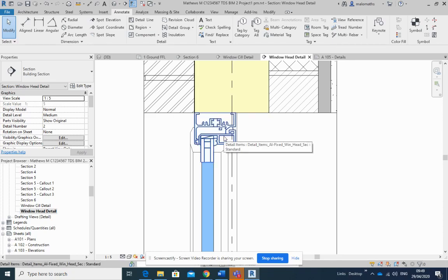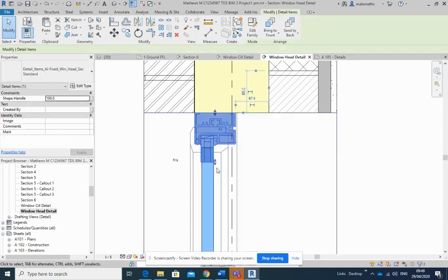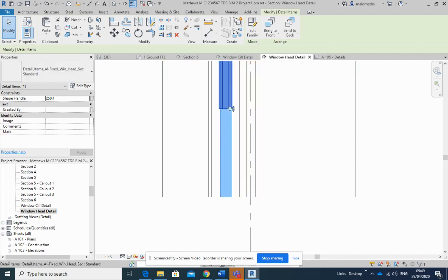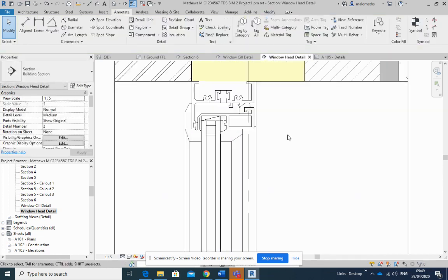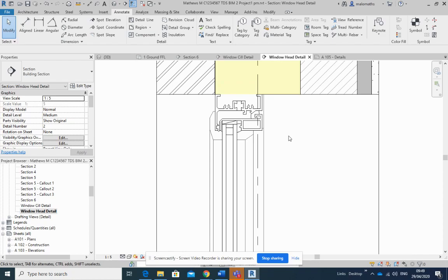This is quite a handy little 2D as well, because it has stretching grips and things like that. So look, I can stretch that double glazing right down past here, so that gives the indication that I'm double glazed here. Let's see, what else is there? You know, if I wanted to put in, say, a facing on that, I could do that.